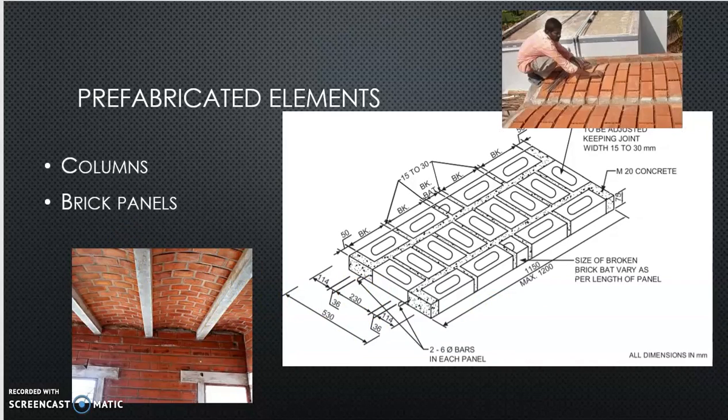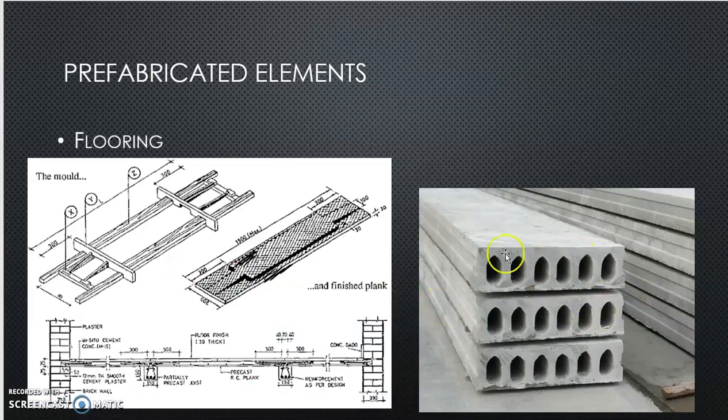Then, alright, did I explain this? Yes, these are hollow slabs. Okay, these are also used for flooring. They are also very sturdy. So you are removing the part of concrete which is not getting stressed, which is not participating in any kind of load transfer. So that is removed. These are different prefabricated elements. Okay, so we are done with the prefabricated and precast subtopic.